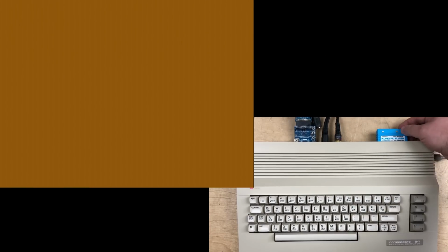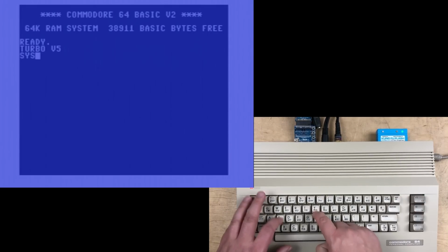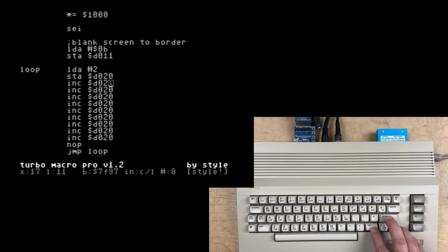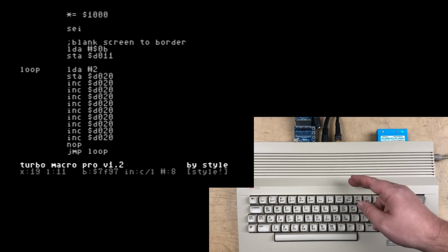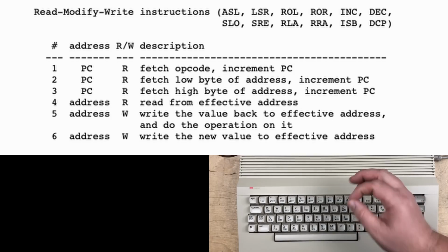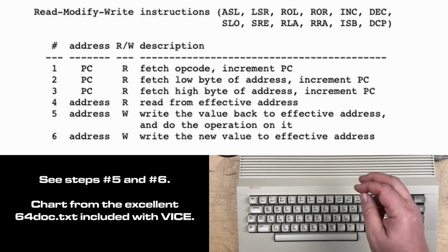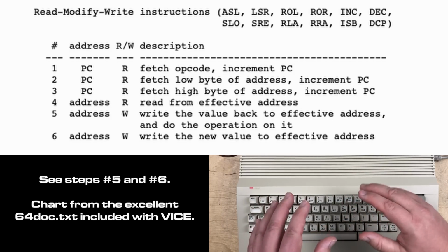It is ugly and distracting, but what's really bad is if you look on the pink or the brown, the blue or whatever, how one character to the left of the color change is a separate line. And those are especially ugly, and that is the bug really at work. And this is due to a quirk of the increment command in the 6502, 6510. It actually does 2 writes to that register just as part of the CPU.